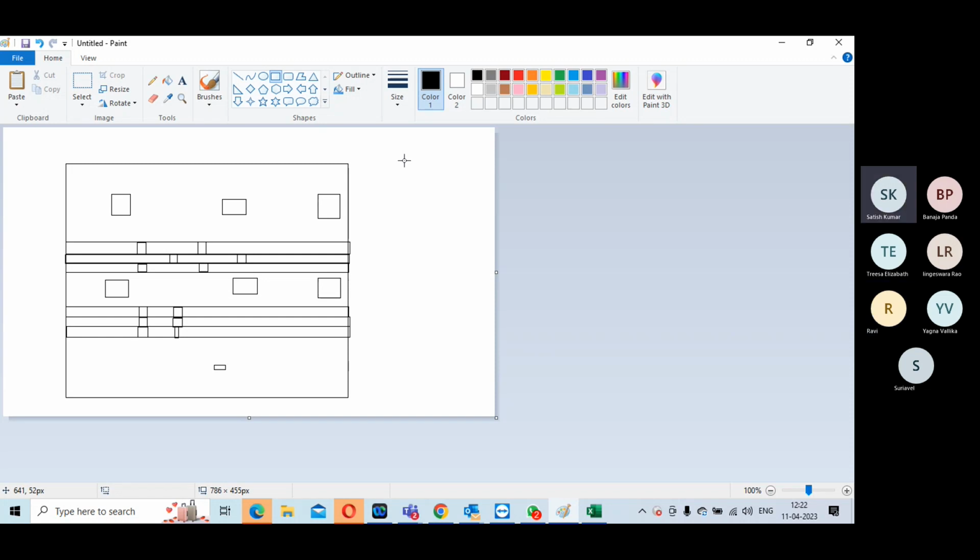Now let's talk about the isolation enable signal, that's the second factor. Enable signal should be connected to always on. In the off domain also, there will be some cells. This is an off domain, a block which can be shut off. Even if it's shut off, certain logic should work.